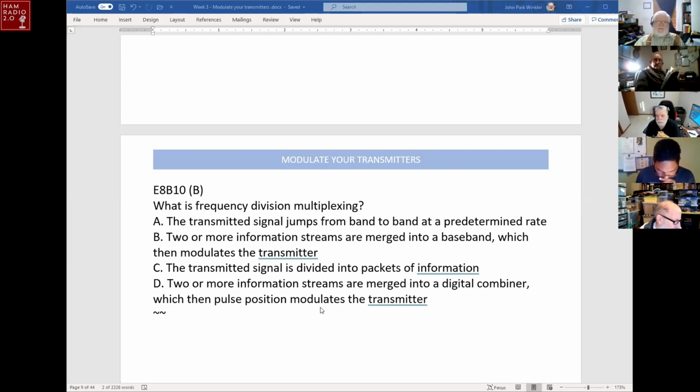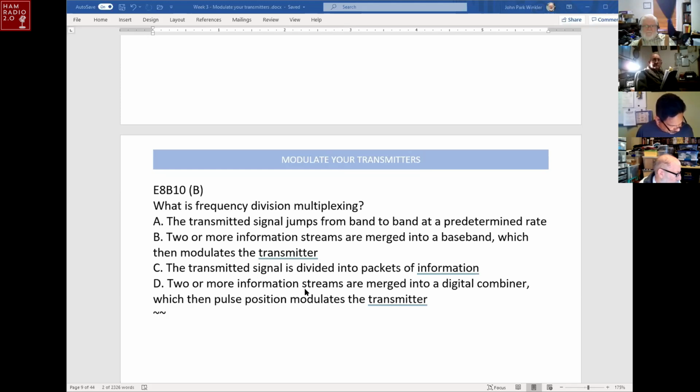Another application is multi-carrier telephone lines, which were the first attempt at getting more than one analog signal on a twisted pair, like to reach out into the country and into the spaces away from big cities, which we called the country back then. So that was years and years ago when that system was in use. And every like 10 kilohertz up to about a couple of hundred kilohertz, there would be an analog signal, which is a voice channel. And at the user end, that would be translated down from the 100 kilohertz range back to baseband, which is the 3 kilohertz phone bandwidth. That's a good example of frequency division multiplexing.